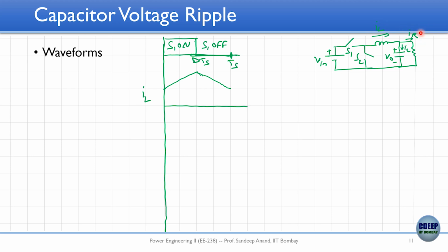What would be this resistance current, IR? How would that look like? Would it look similar to IL? Would it look different from IL? How would IR look like? It looks similar to IL. Okay, next person. Constant. Next person. So all of you agree, right? IR would be constant because of our previous assumption that output voltage ripple is small.